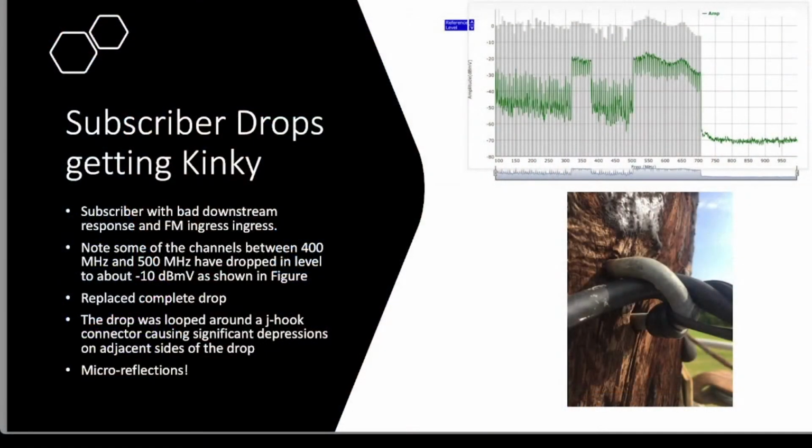So the ingress is so bad you named it twice. The first bullet point says FM ingress. I'm like, okay. Yeah. Also, that was some of the other thing that's going on. If you look at the low frequencies, and I didn't zoom in on that, there was a lot of FM ingress coming in. So I think there was enough abrasion in this, or I don't remember exactly if it was from a loose connector down at the house, but this also allowed FM ingress to come in at the very low frequencies.